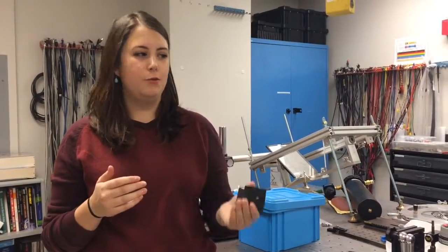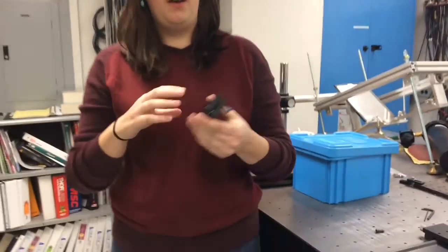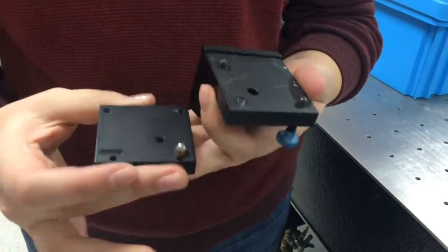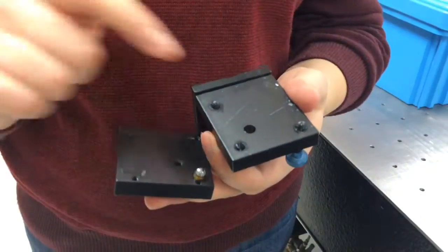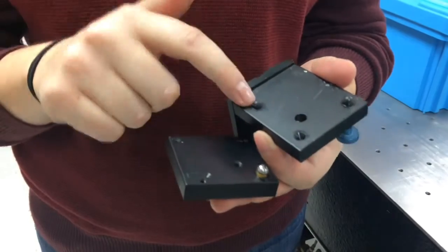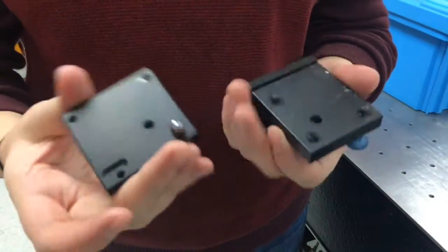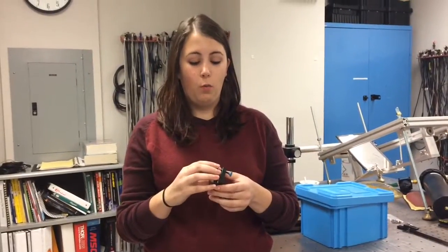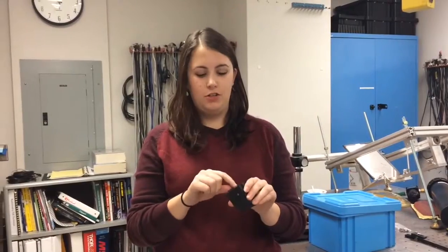So now we're going to talk about how kinematic constraints can relate to mounts, especially for optomechanics. This is a simple tip tilt stage, but when you take it apart, you can see that it is constrained by a ball in a cone, basically a part of a sphere in a V, and then a part of a sphere on a point. That perfectly kinematically constrains it, and that means, in theory, this should have one specific location only for each turn.